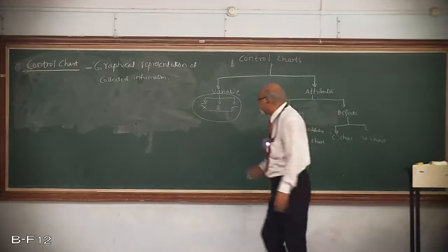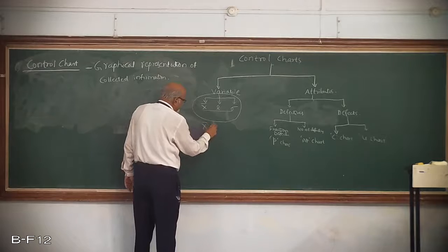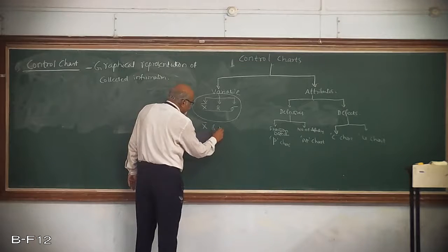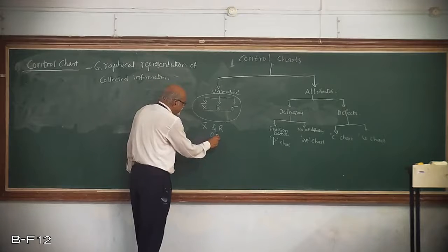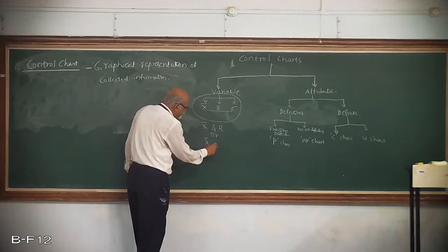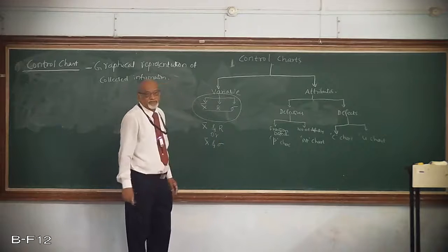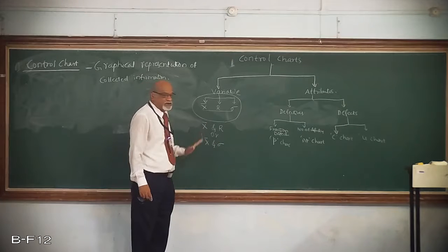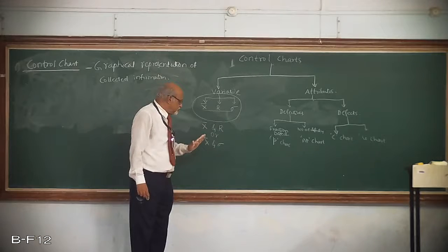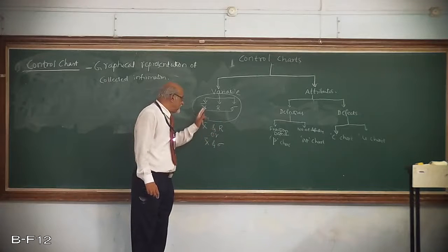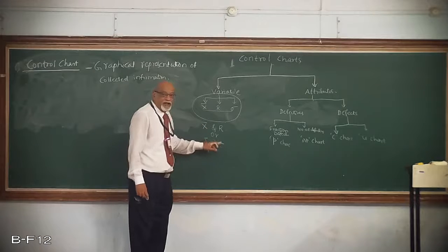It has to be used in pairs. That means X bar chart in conjunction with R chart, or X bar chart in conjunction with sigma chart. I cannot just use X bar chart. I cannot just use R chart. I can use either X bar and R or X bar and sigma.